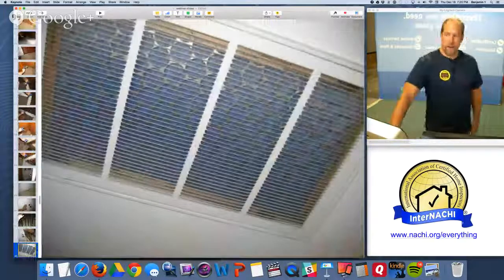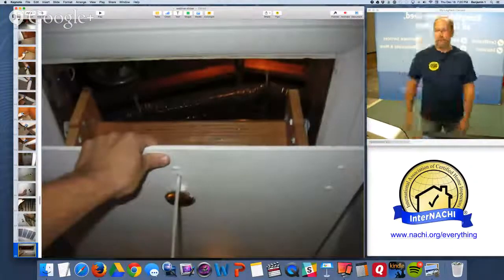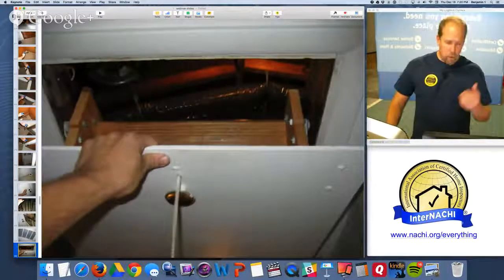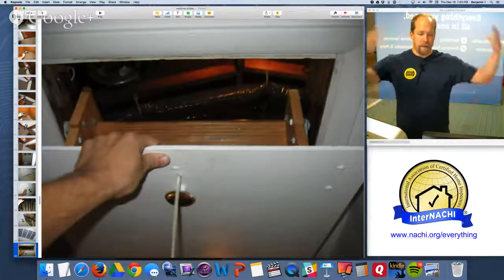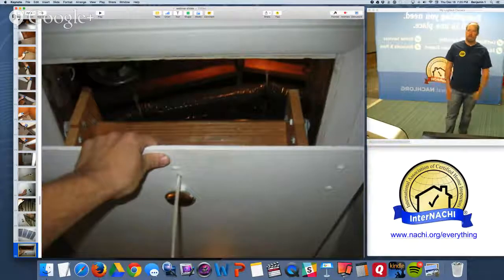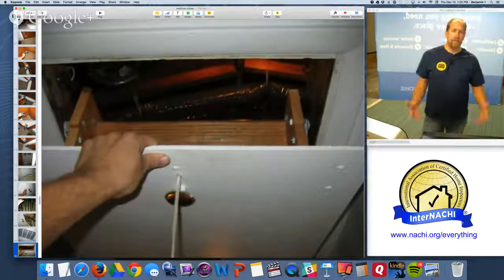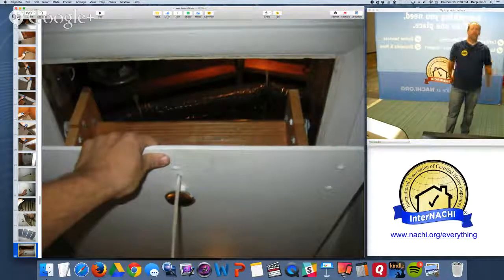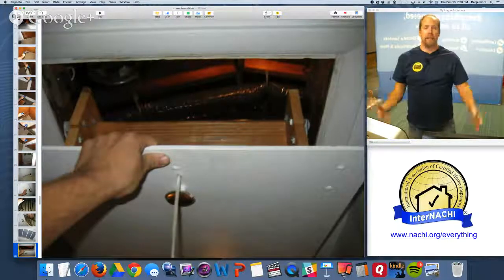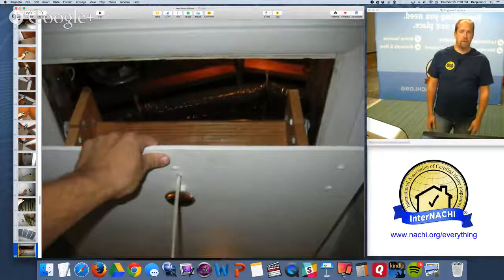There's the attic air handler. Air filter is in the ceiling of the second floor. Pull down stairs, totally inefficient. It's not insulated. Doesn't have a nice seal around it. The pull down stairs is not insulated itself. There isn't a cover on top. This is essentially a huge, big 3x5 hole, 15 square feet. It's like an open window, essentially, allowing conditioned air to escape naturally through stack effect through the attic floor, which is not insulated. It's not insulated, it's not sealed. It's like having a window open in the middle of winter, right?